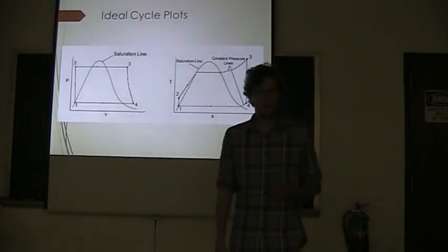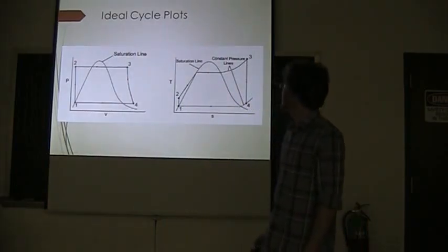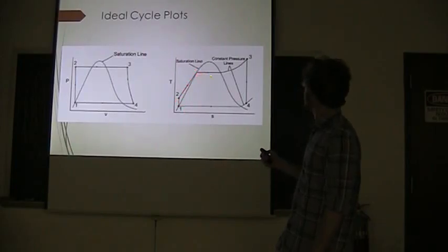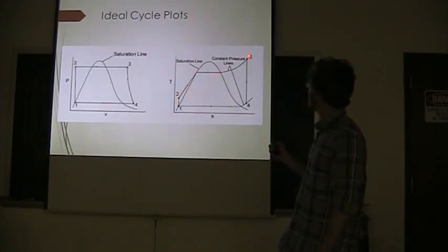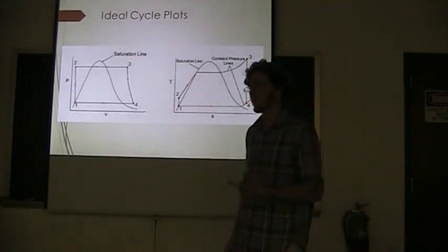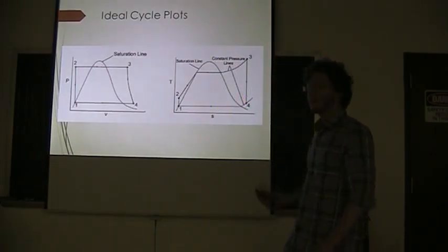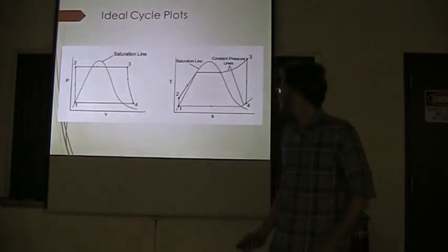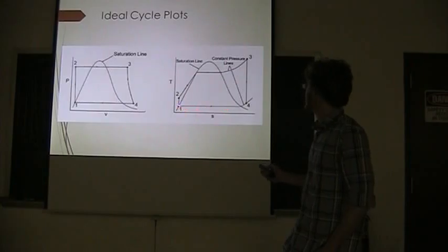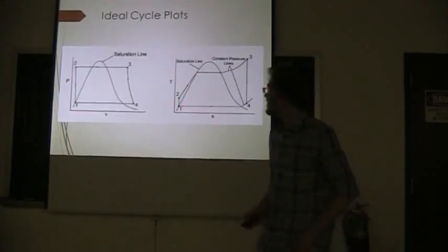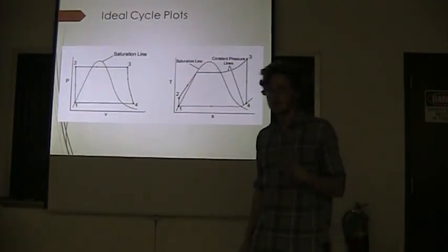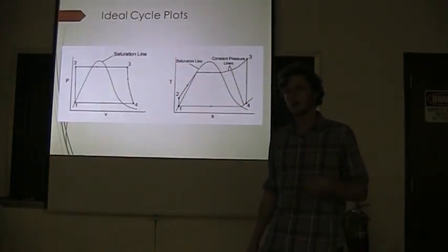In the ideal cycle, it works like this: you pump it up to a high pressure, you expand it, so it boils here from water to a superheated vapor. The turbine is here, it drops the temperature. It's where we actually get our energy out of. And then in the ideal cycle, which is a simplified model where everything was not completely connected, you would pump it back here, and basically decrease it when you condense the water vapor back into water, where you can then repeat the cycle by